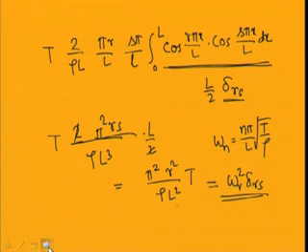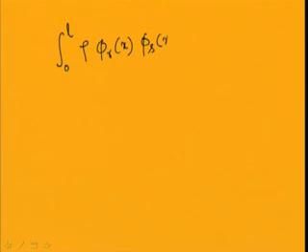So, we have seen the mode shapes are orthogonal, and from this also we have checked that the integration 0 to L of rho phi r x phi s x, where phi r and phi s are the rth and sth mode shapes, is equal to delta r s when r, s equal to 1, 2, and so on. So, you can take any number of modes.